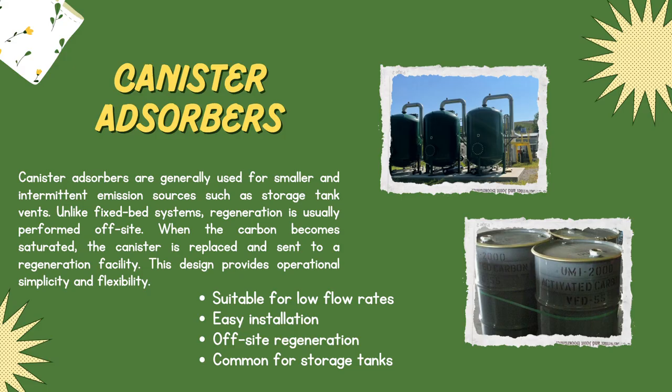Canister adsorbers are generally used for smaller and intermittent emissions, for sources such as storage tanks and fans. Unlike fixed bed systems, regeneration is usually performed off-site. When the carbon becomes saturated, the canister is replaced and sent to a regeneration facility. This design provides operational simplicity and flexibility.